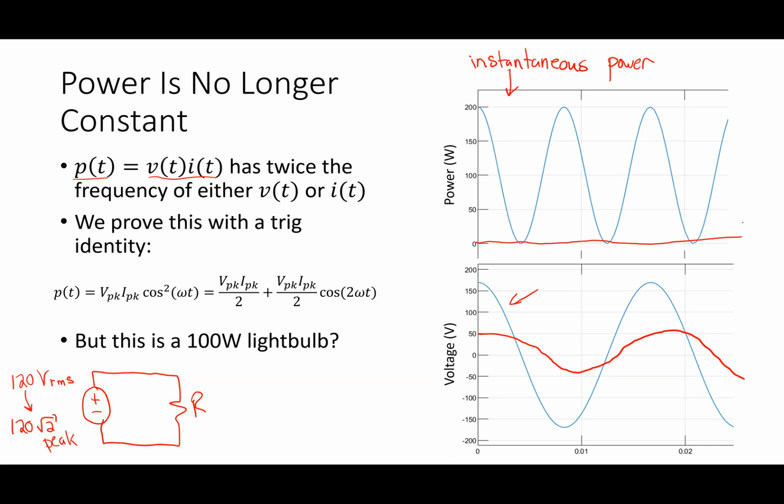Now, what we talked about though is the situation can change a little bit. This guy right here, that picture I have at the top, how does the frequency of that relate to the frequency of the voltage? Twice. It's twice. All right, that's twice the frequency. And the formula specifically, if I talk about the peak values here, is written out like this, right? In this case, the current and the voltage are in phase with each other, so I get this cosine squared, so it becomes this whole thing. Now we're not gonna do trig identities with this. We're gonna jump away from those today, all right? But we see some important results with this.